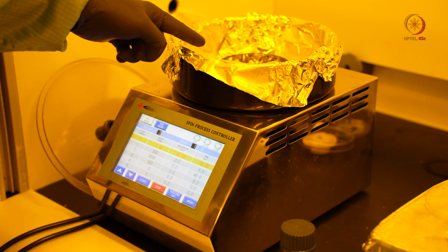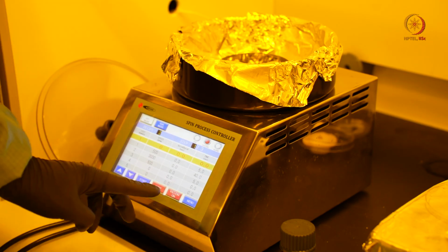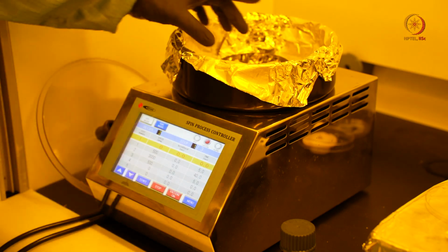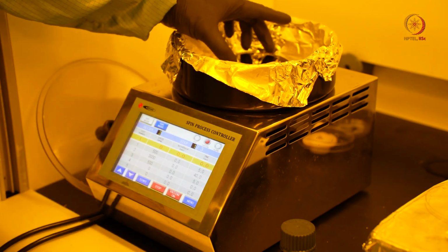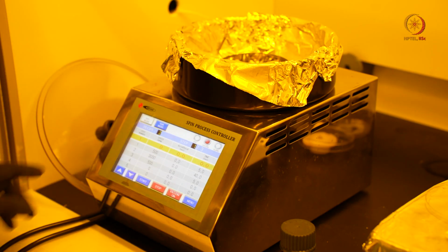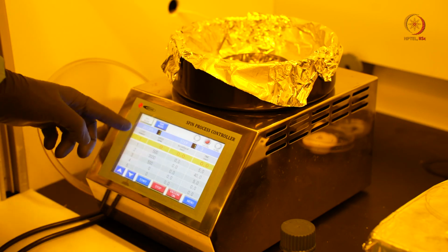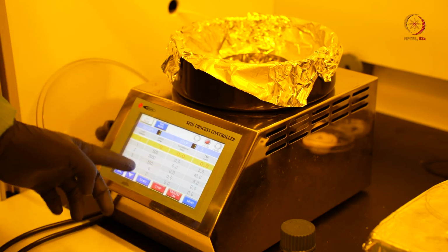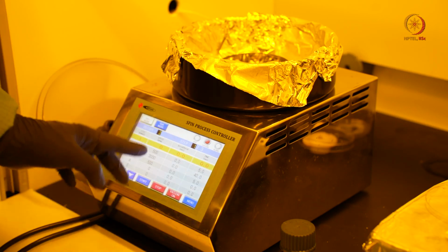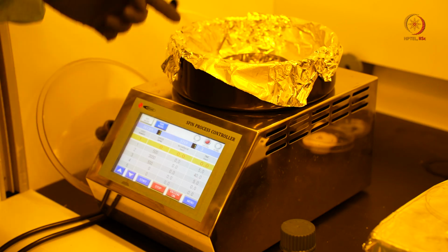Okay, now since I have loaded the wafer, I am going to create the vacuum. So I have switched on the vacuum. Now if you see, the wafer will not move even if we try to push it. That's because the vacuum is on. Now we can go to run mode, where if we press start, it will start rotating. Now before that, we have to pour the photoresist over the silicon wafer.